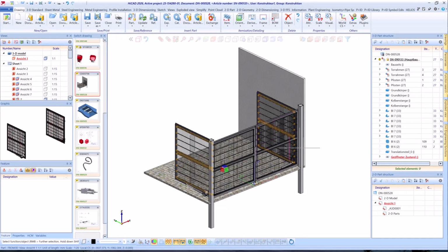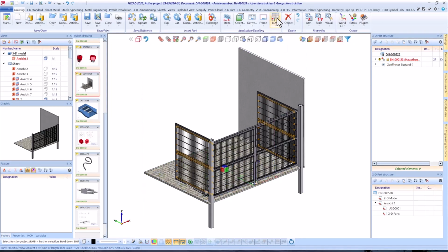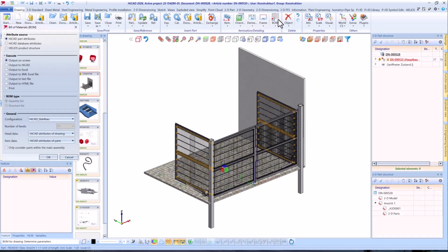If you want to exclude auxiliary or environment parts from the bill of materials without changing their value, then you can now simply move the parts out of the main assembly. When itemizing and creating bills of materials, you can now limit the selection area to the main assembly. The advantage of this is that the bill of materials relevance can now also be transferred via referencing.